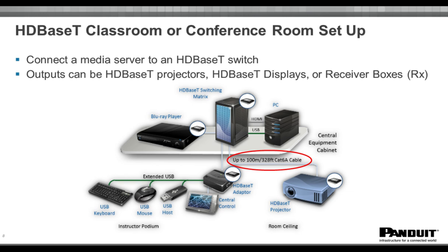A lot of the projectors on the market today, AVIXA actually says over 95% of the projectors on the market today have an HDBaseT input. This is really great because what it means is you don't need a receiver. You can run a transmitter through or not through a matrix switch and straight into the back of that projector.